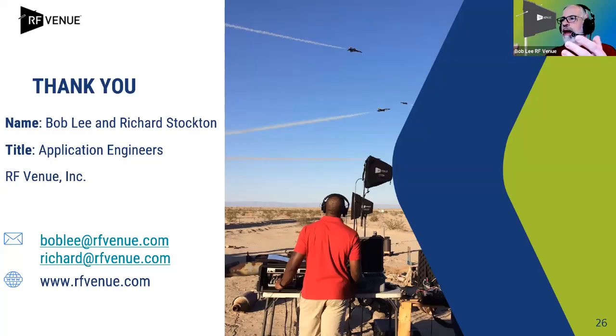But we recommend, for receiving, you need a diversity pair of antennas. Now we have the diversity fin antenna, which is a polarization diversity antenna, because the angle of polarization of the signals hitting the antenna will vary with the transmitter moving around.